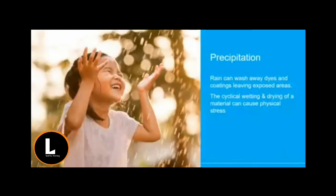So the final environmental factor to consider is precipitation, otherwise known as rain, which we've seen a lot of in the UK in the past few weeks. When conducting weathering testing, the basic light fastness test sees the addition of a water spray to replicate rain conditions. This is known as colour fastness to artificial weathering, which is served by the standards ISO 105 B04 and also AATCC 169.